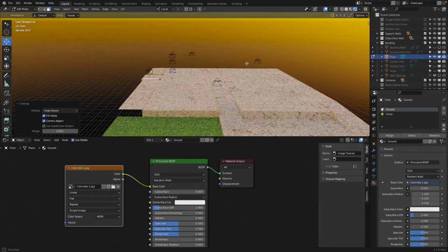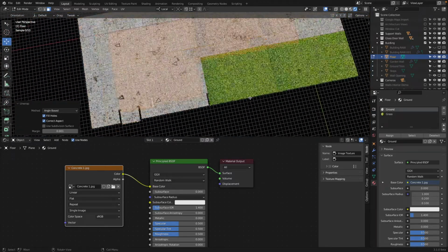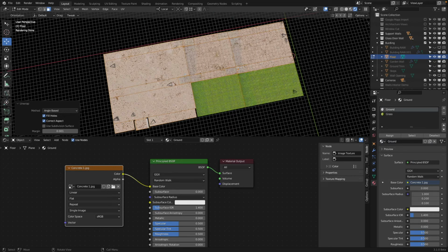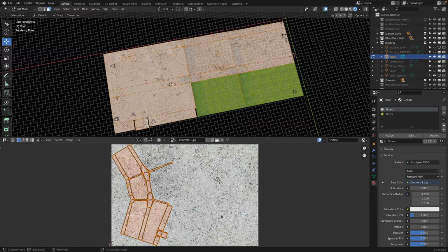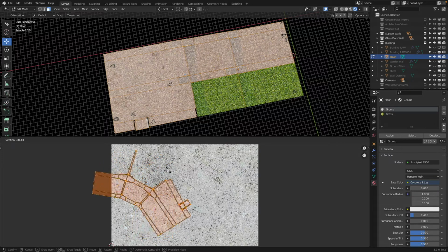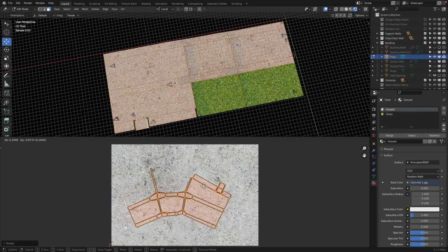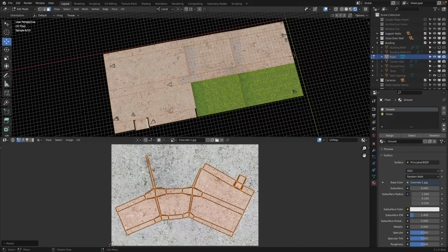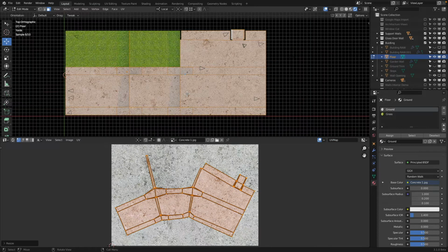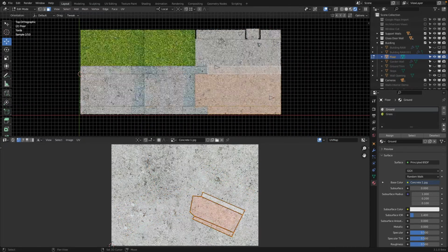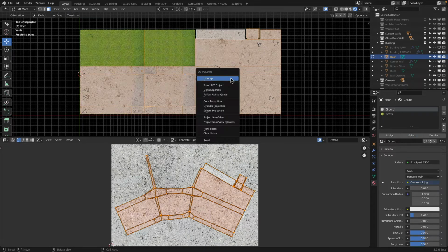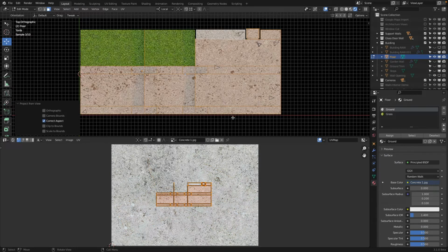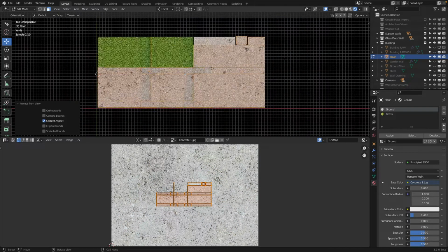It's really large. So the main thing is this whole geometry we took and mapped over that image. And there you can see here's actually my space. I can even rotate this. This is kind of like the UV unwrapping. I can go to maybe a top view. When I select these faces, you can see what's actually selected. If I do a UV unwrap from view, then it's actually more linear.